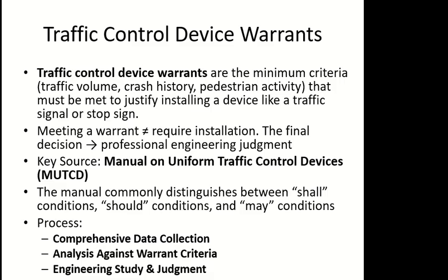But you are still facing a lot of delay on the intersection. So you may do an additional study to know the reason. So whether the warrants are met or not met, before you go on and install the device, you may do an additional study to further know what is actually happening on the intersection.